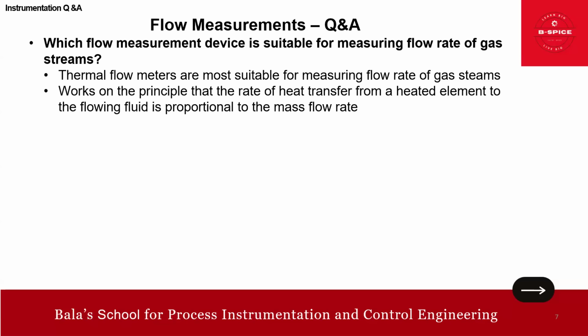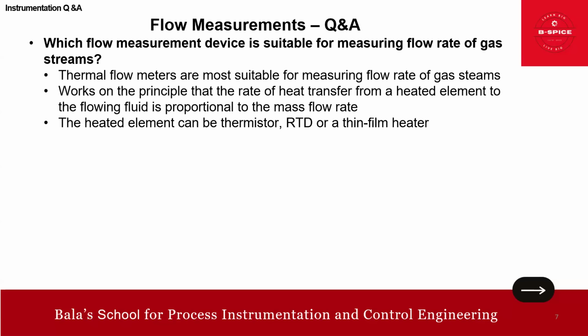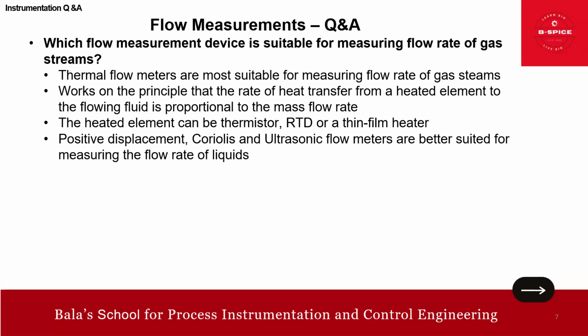So basically, it works on the principle that the rate of heat transfer from a heated element to the flowing fluid is proportional to the mass flow rate. That's it. The heated element can be a thermistor or RTD or a thin film heater. Okay. So another point.